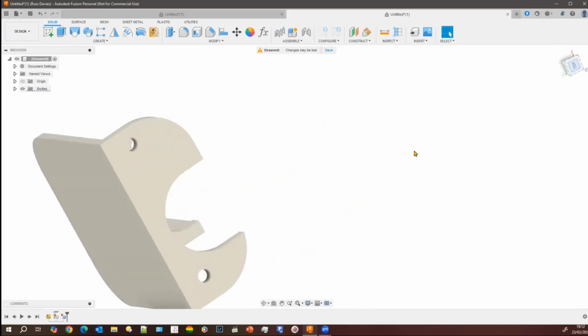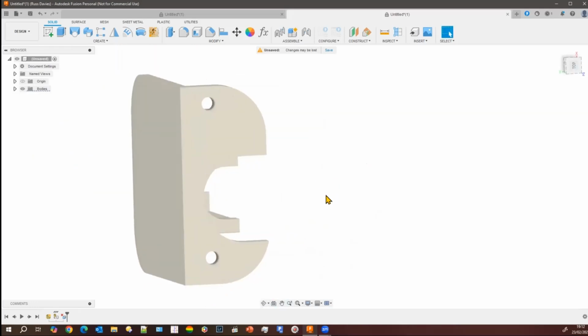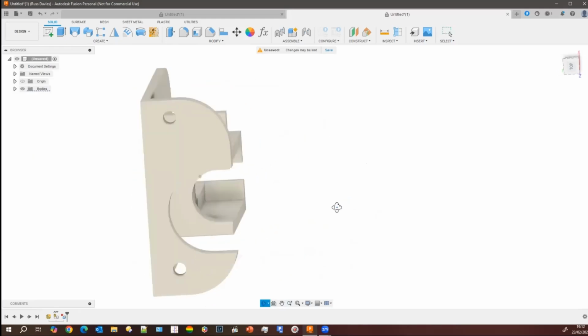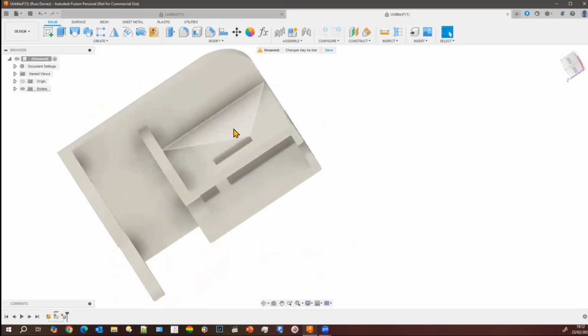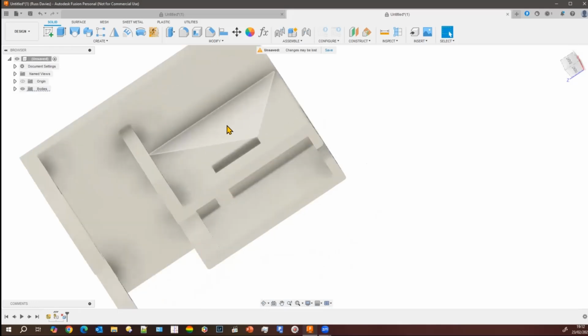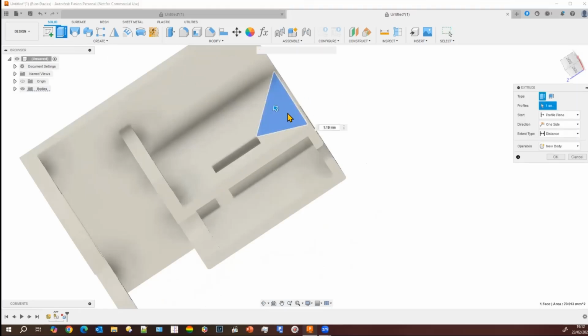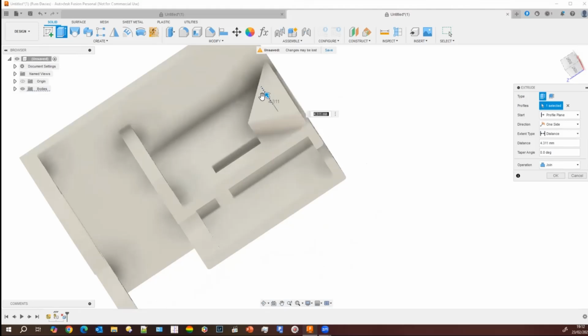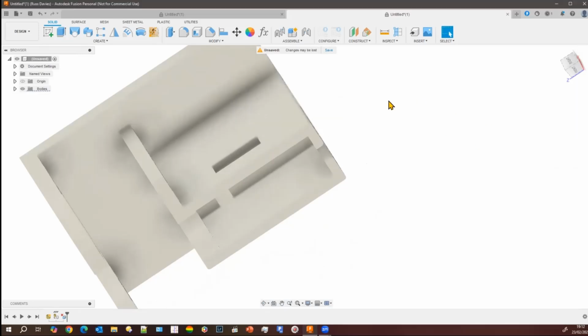So let's just look at another one. Let's get things in shape. If we look at this face again, that's one face because it's come on with that one. If we come in here, you can see on this face we've got a whole pile of triangles. And as I say, if we highlight the one and we try and enlarge it or alter it, we can't do it. On the other hand, if we hit one of the triangles and delete it, that face becomes one face that we can then edit with our normal tools.